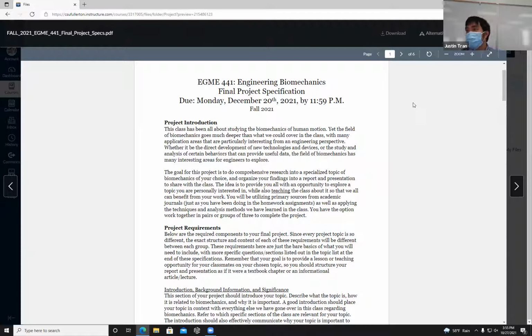Yep. So I'm doing the wall bracket analysis class. I did a simulation, but did not exceed the stress, did not exceed the yield strength, but the deformation was like a meter. I'm assuming that the bar could just bend without breaking apart. Is that a possible situation? A 1 meter deformation is pretty big though. Yeah, it's even giving an error warning saying deformation error or something. Yeah, 1 meter usually, because it's not that big of a wall bracket, is it?